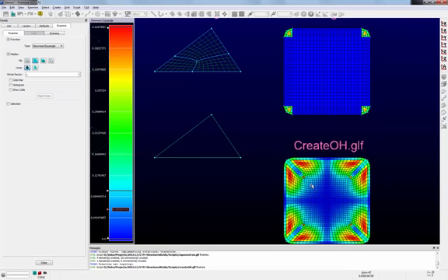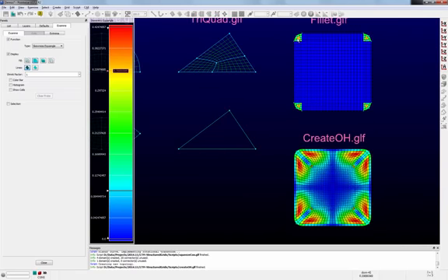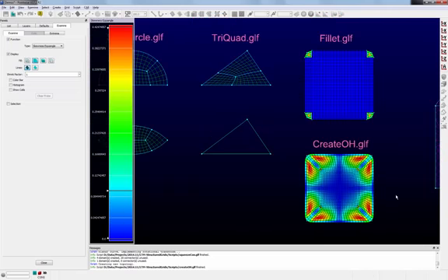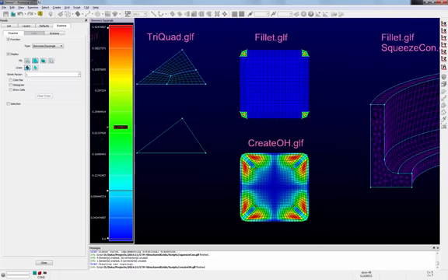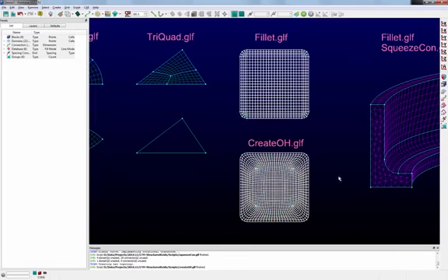So it really depends on your particular circumstance, what you're trying to get after. If you can afford this additional topology here, you can wind up with a higher quality grid overall and confine the problem areas to a very small local point. Or you can use a larger global script that will produce fine results. It's just, again, a matter of balancing your cell quality and your solution accuracy.